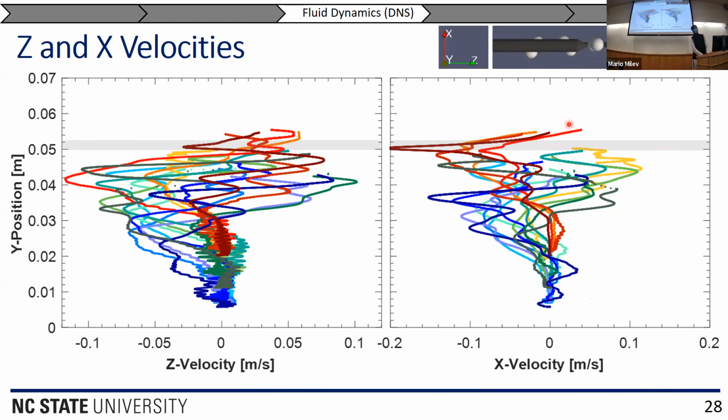For the bubble simulation, you are solving the Navier-Stokes equation for the air or for the water? Could you repeat that? You are modeling bubbles, so you are solving the NS equation. That's for air or for fluid? Oh, the Navier-Stokes is solved for both. We use the level set method, which is a one-fluid method. So you have essentially one set of equations for the whole fluid, both the air and the liquid. Then near the interface, the properties are smoothed out to go from properties of air to properties of water. Okay.